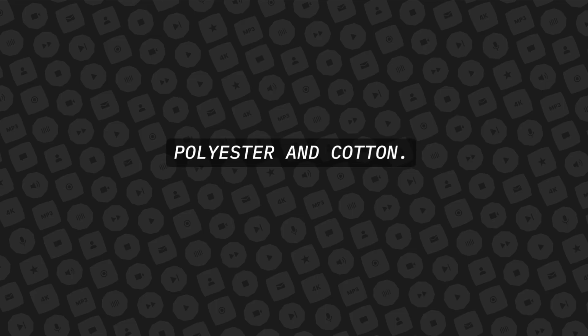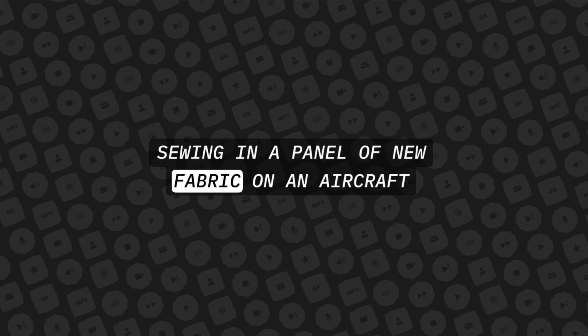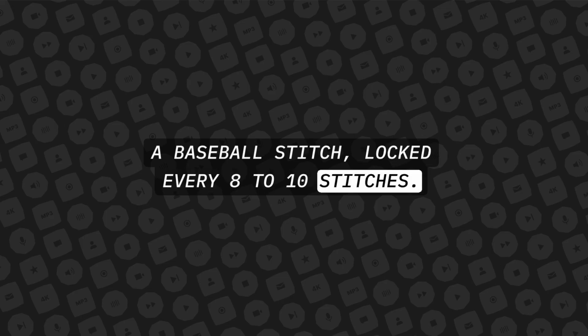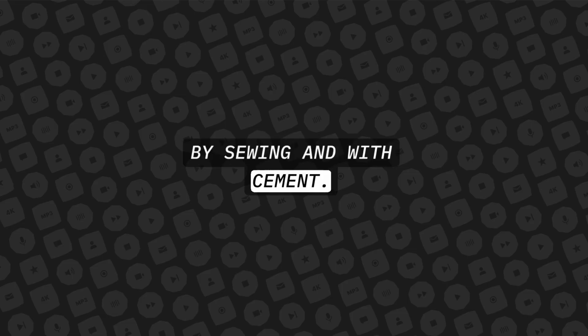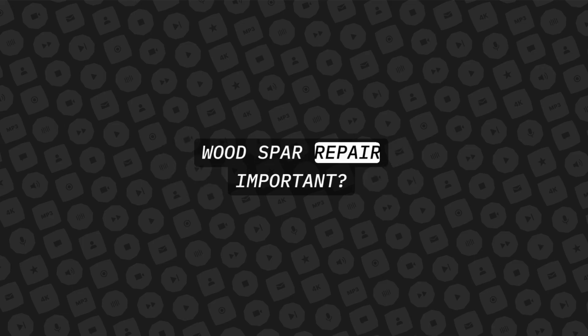What are two types of fabrics used to cover aircraft? Polyester and cotton. What type of hand sewing stitch is used when sewing in a panel of new fabric on an aircraft fabric covered wing? A baseball stitch, locked every 8 to 10 stitches. What are two methods of attaching the fabric to the aircraft structure? By sewing and with cement. Why is the scarf joint angle and condition of wood spar repair important?